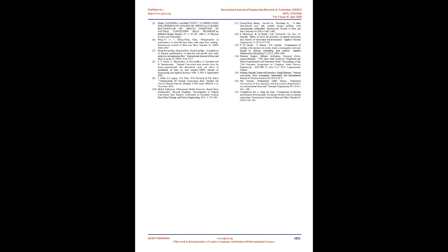The most frequently used coolant in the microchannel heatsink is air. Better results may be possible with other fluids. So, one of the methods for changing heat transfer is to use different working fluids. Effects of heatsink geometry. It is investigated that the maximum fin temperature decreases with the increase of the number of fins in the array. But after a certain increase of the array, the temperature of the assembly again increases. It is because the coolant does not get enough space to take the heat from the array.